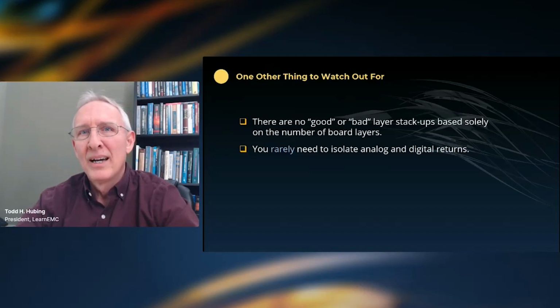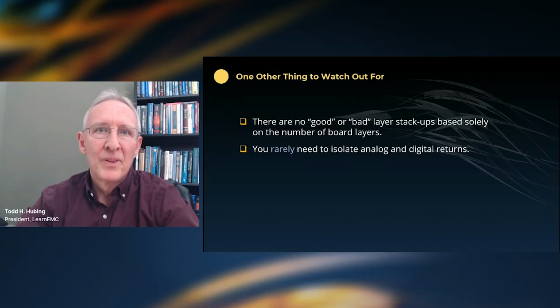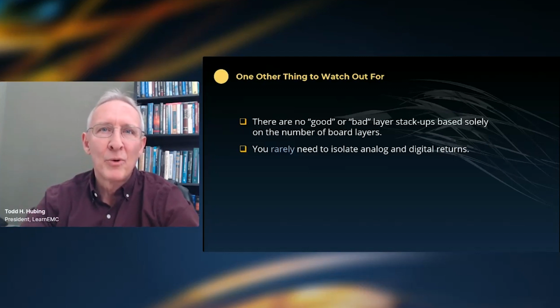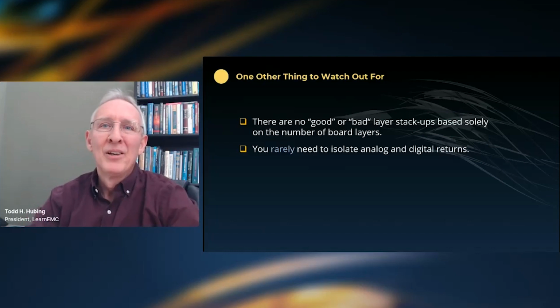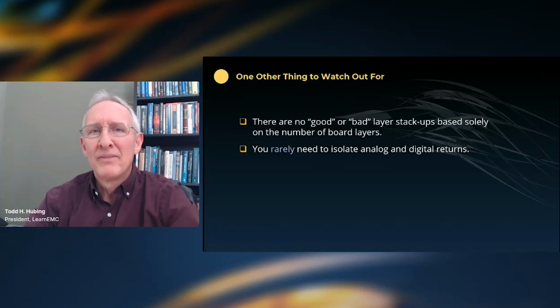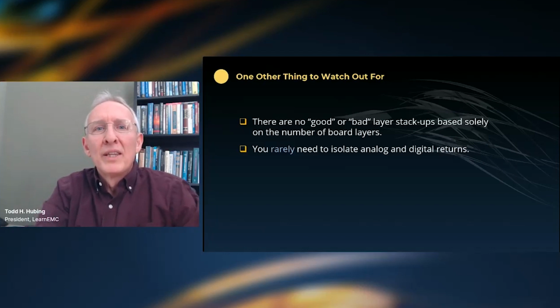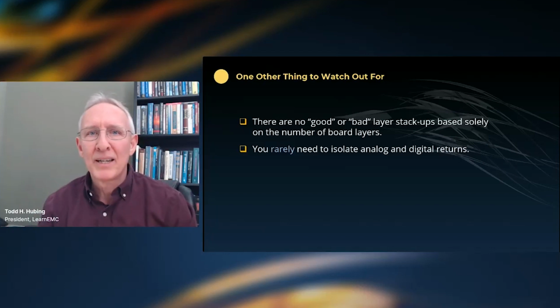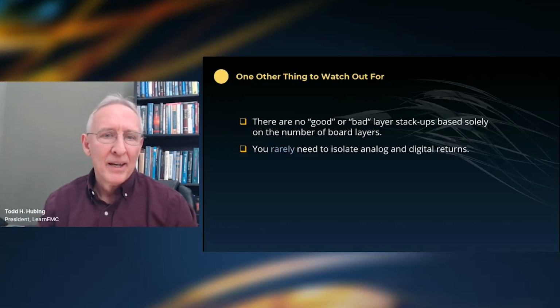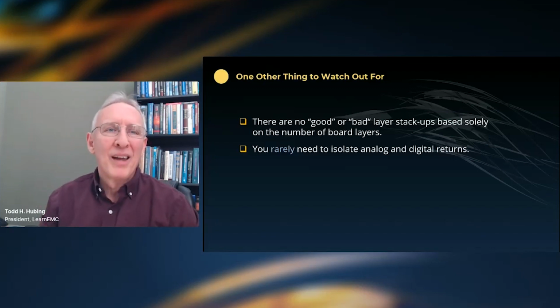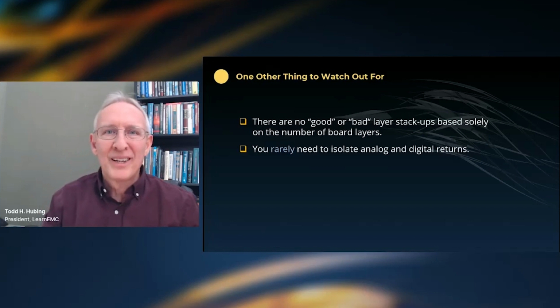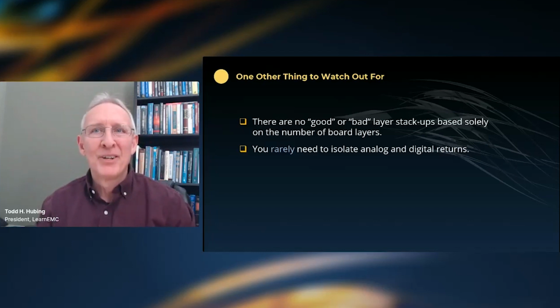I mentioned the one where the power and the ground in the 6-layer board were separated by several layers. Sometimes that's exactly the right thing to do, and sometimes that's a terrible thing to do. But be careful about the advice that says avoid this stack up or this is a terrible stack up. I just don't agree with that. It's exactly true for some kinds of boards, but I work with a wide variety of boards, and there is no rule about the stack up that always applies.